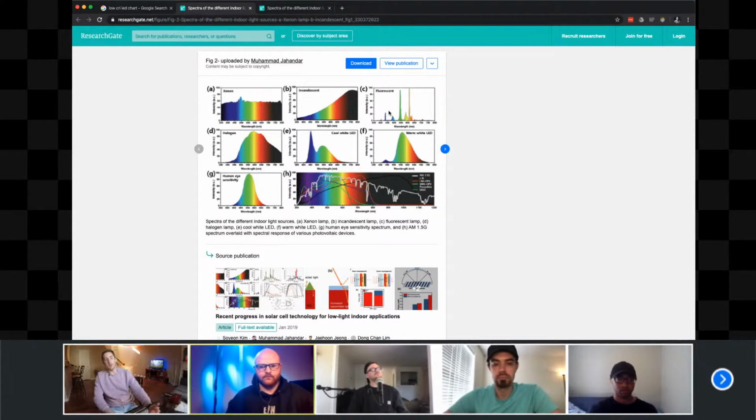And so whenever somebody grabs an LED fixture off the shelf in Guitar Center and puts it up in their church, and they wonder why all of a sudden all their people look green and sick, and that didn't look that way in Guitar Center. Well, it's because your cameras are picking up those green spikes more than your human eye is.